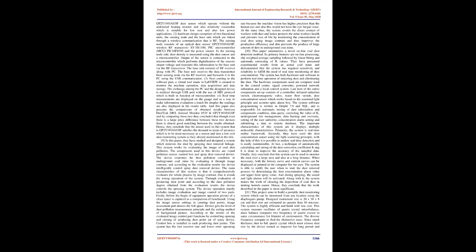The base unit consists of an RF receiver along with a PC. The base unit receives the data transmitted from the sensing node via the RF receiver and forwards it to the PC using USB communication. 3. Next, coming to the software part. A virtual tool made in LabVIEW is created to monitor the machine operation, data acquisition, and data storage. The exchange between the PC and the designed device is realized through the USB port with the use of HID protocol, which is a built-in function of the microcontroller.